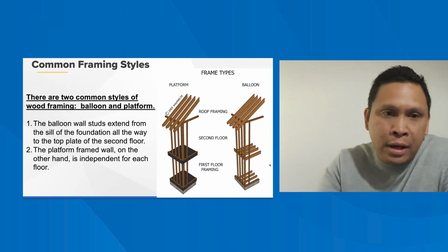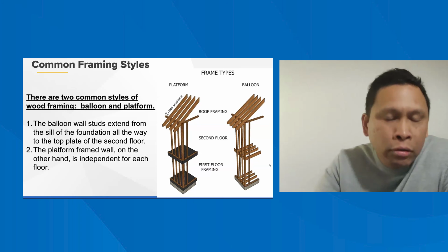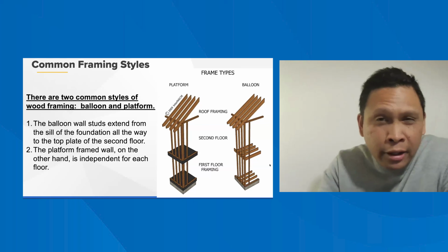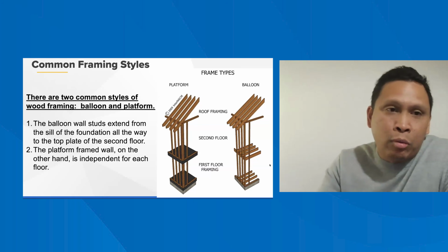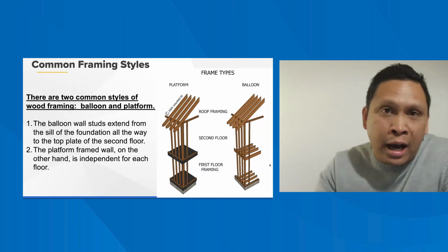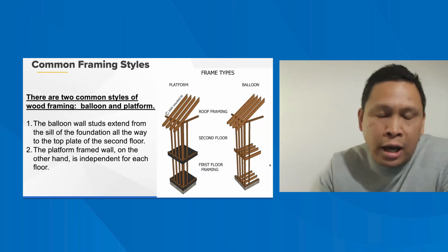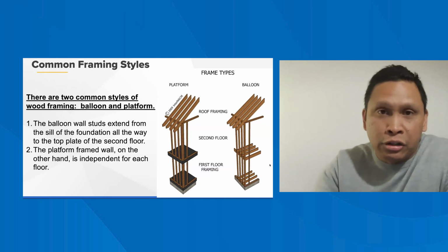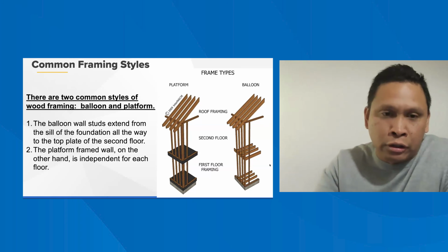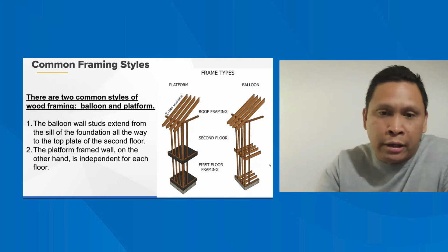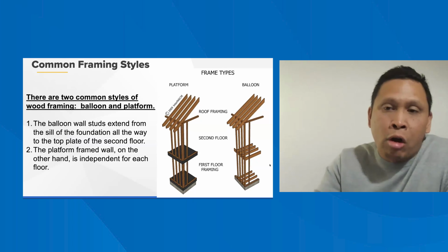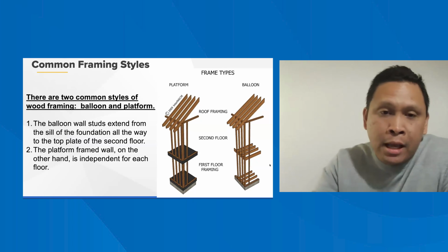Most of the time, if you're going into a newer style home, you'll most likely encounter an I-joist system. I think the most common one that you would see is a TJI. It's almost like saying Kleenex instead of calling it a tissue, because it's just everywhere. But TJI joist is what you would see there, or you would see an open web floor truss system.